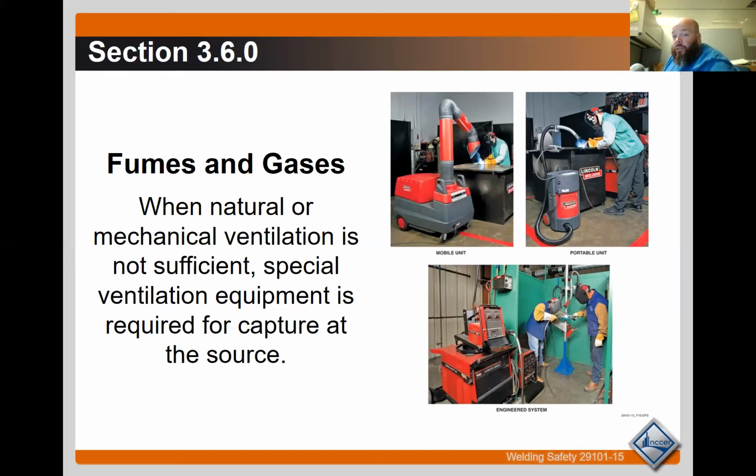Another thing you want to do while welding is keep your head out of the plume of the smoke. You don't want your face directly over where you're welding, so the smoke's coming up into your face. One, because there could be hazardous, toxic materials in the plume. The other thing is that it also really dirties your mask and makes it hard to see.